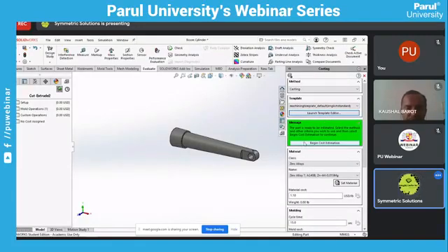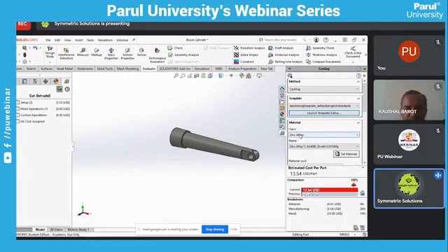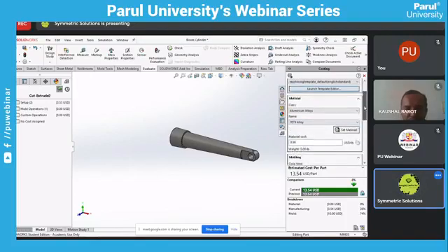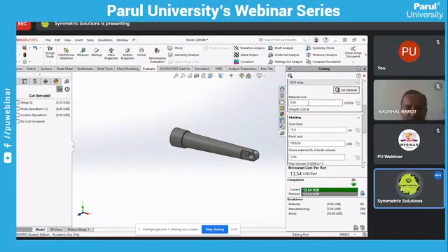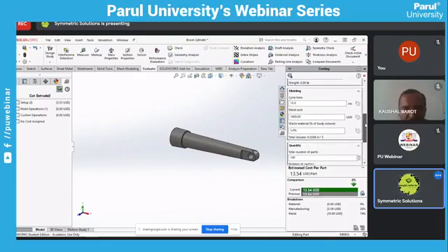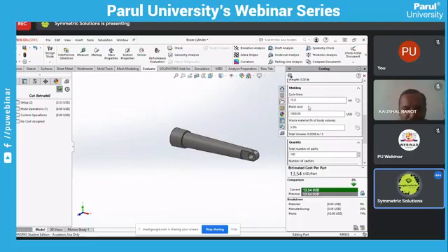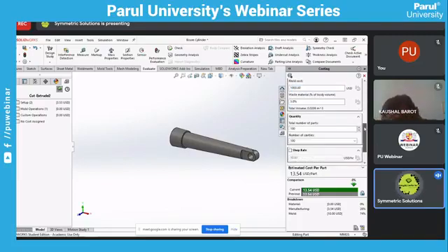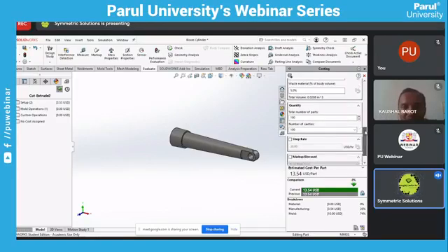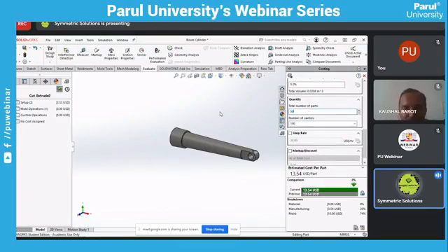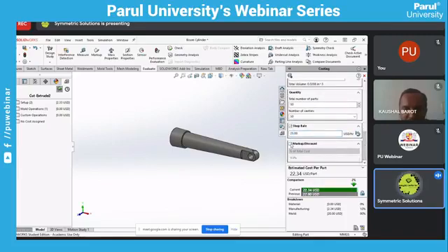Now begin cost estimation. As per class, material is some other alloys, and apply some aluminum alloys. Define your material, and material cost is something like 0.9 USD per pound. Molding cost, cycle time is 15. Mold cost is 1000, as per our input. Waste material is as per our input. Quantity, how much quantity you need? I need 50 quantities. If you want to add some shop rate, that is $25 per hour. If you want to apply some discount, then again a discount of 10%.